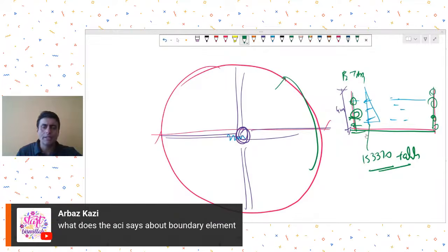Now in software like STAAD, we used to go for only load transfers as if the slab was membrane like, because the analysis engine was not that much developed. So we used to go for normal load transfer and would not model the slabs, and just transfer the loads onto the beams.